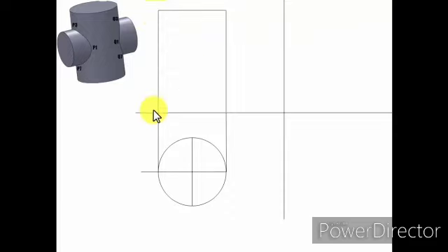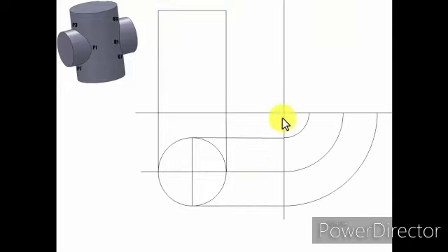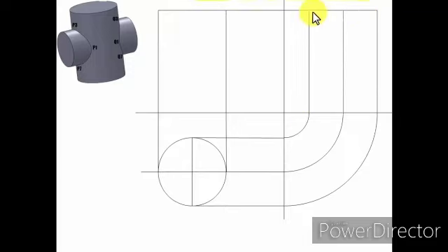This height I've assumed to be equal to 120 millimeters, and this width is obviously equal to the diameter, that is 80 millimeters. Fine, let's go ahead and create the left hand side view. It's going to look something like this. Let us rotate that about this center. Let me get a vertical line in this direction, and a horizontal line, and this intersection, this rectangle, is again what you call the side view. So the front, top and side view of this vertical cylinder is over.